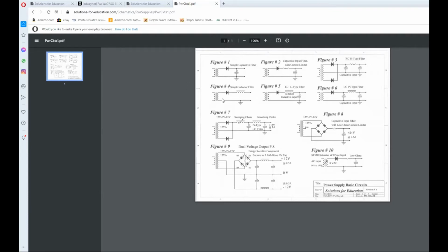Now, down here, we have a whole other story. This coil that's here serves a definite purpose. With surge currents, the coil says, you're not going to push that current through here. A coil is an open circuit to begin with, so that by itself is not going to do much filtering, but we add this capacitor here. Now the two of them together work real well,